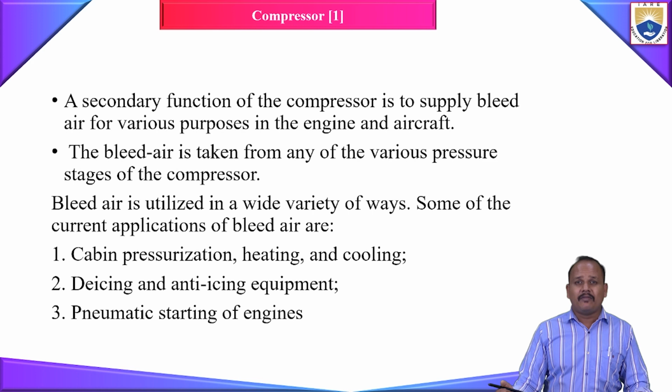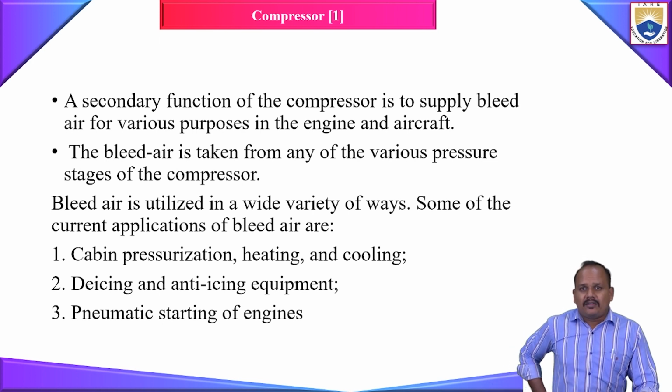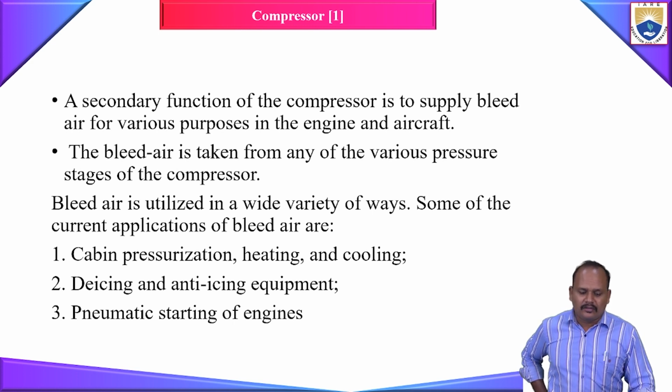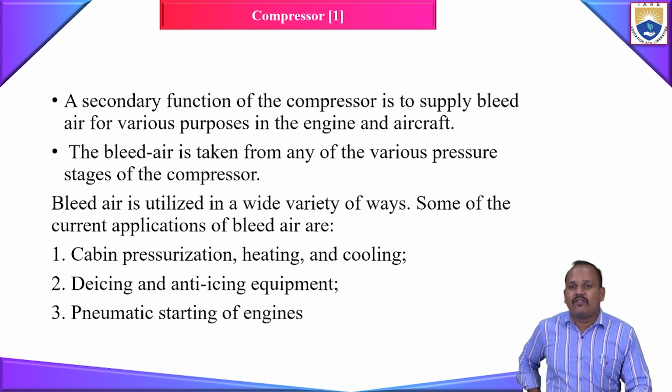Another one is the pneumatic starting of your engine. Pneumatic starting of your engine means the high pressure air will be used for starting your engine. So these are all the secondary purposes of your bleed air from your compressor.